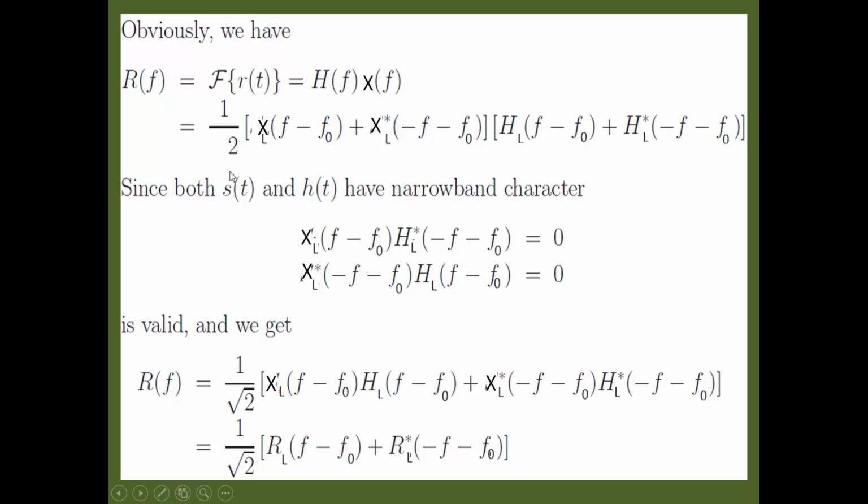So about the scaling factor: for getting the system, the explanation about the system, we did not multiply it with 2. But for getting the input signal, the representation of the bandpass signal and the baseband signal, we multiply it with 2 for getting the positive side of the spectrum.